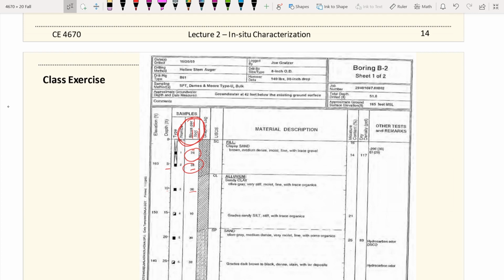And remember, changing SPT-N to N60, you need much information like hammer energy and also the borehole diameter, and so forth. So this may give you some hints on how to get those C sub E, C sub B, C sub S, and C sub R. So this is what you need to find out if you are given historical data.